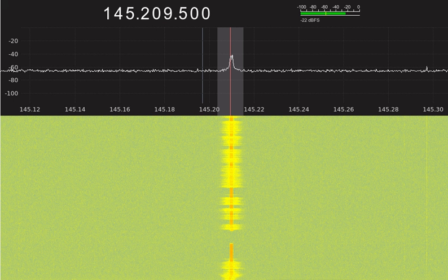What is the approximate length, in inches, of a quarter wavelength vertical antenna for 146 MHz? A. 112. B. 50. C. 19. D. 12. C. 19.